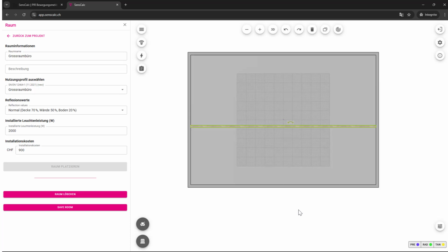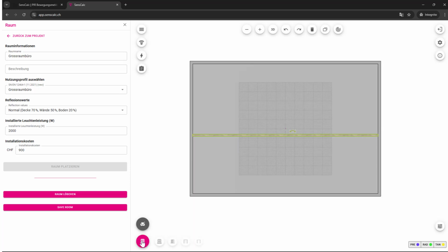Use Add Elements to Wall to add windows. Modify these windows via the Open Panel command located on the right.